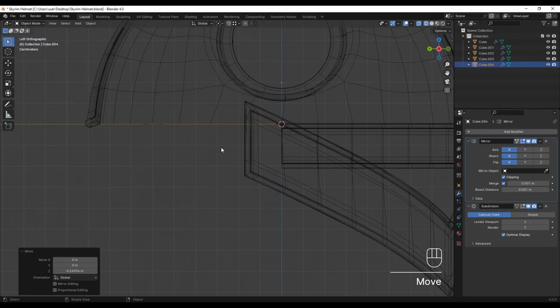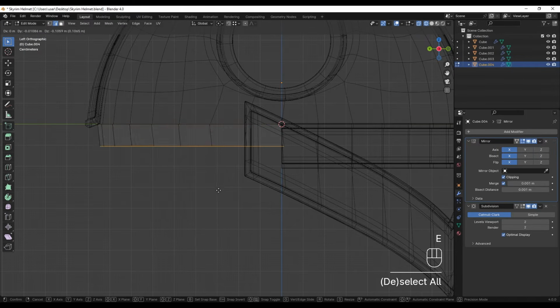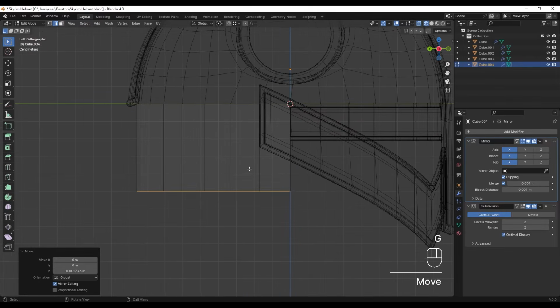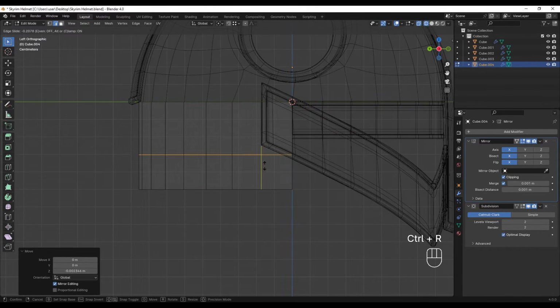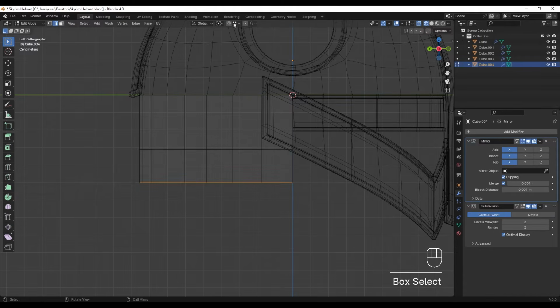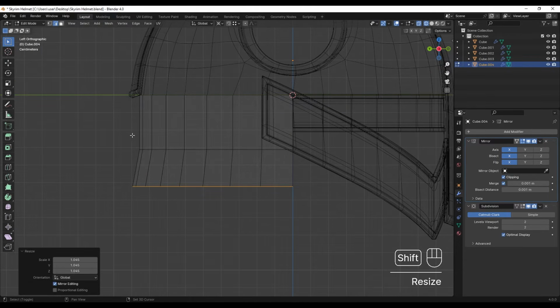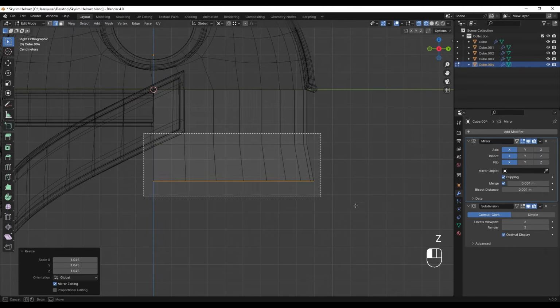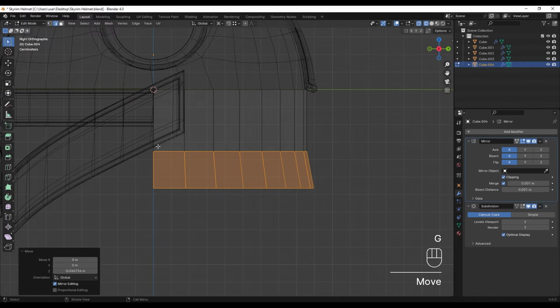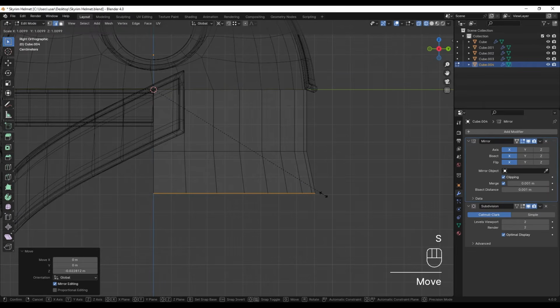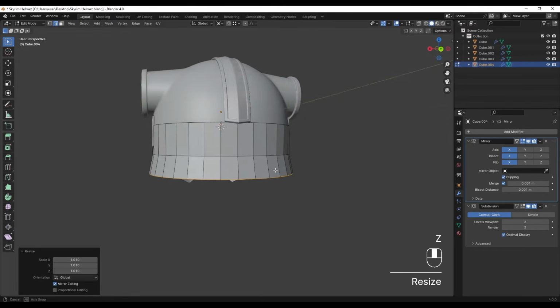All right, then let's go to edit mode, select all, E for extrude, and put this down here like so. And I'm adding an edge loop here, then selecting these, put this on 3D cursor and scale this up a little like so. And we can put this down a little from this section. So put this here and also this one, a little scaling and something like this.